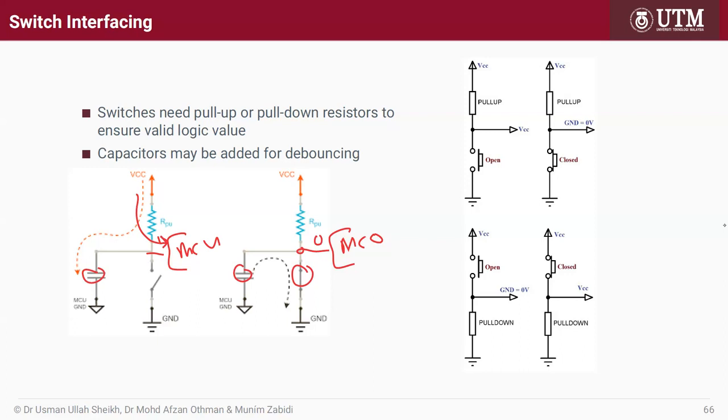Okay, so nowadays, because of CMOS, you can have symmetrical high and low. So you can also do this type now. If you press, you will get VCC. If you don't press, you get 0. For TTL, this is for TTL. A long time ago, this is the only method you can use. Now you can also use the bottom method, but you can still use the top method if you want.